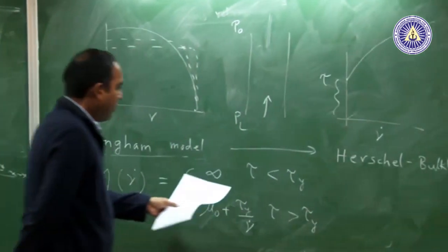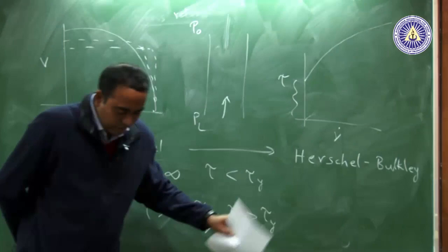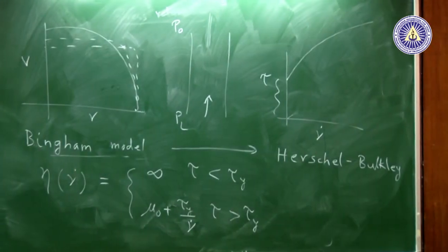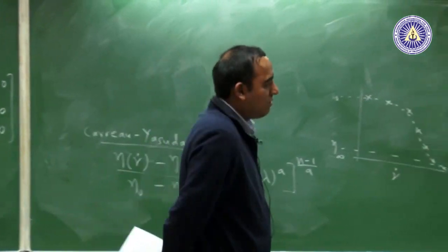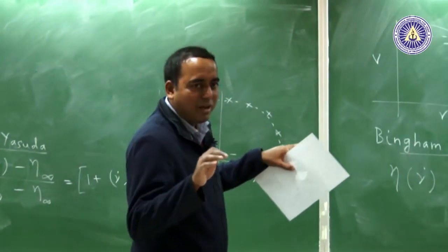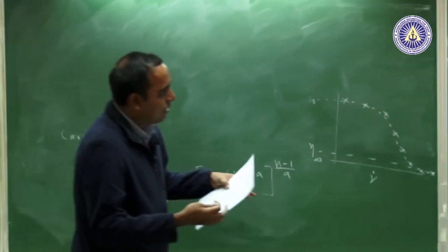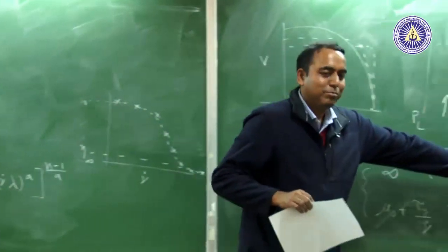but anything beyond a simple flow problem becomes a little bit more tedious. Now, Herschel-Bulkley, I think, is very relevant for the petroleum industry, and Bingham is the typical generic fluid that we have which has yield stress. Anything beyond that, you need something like a Herschel-Bulkley.